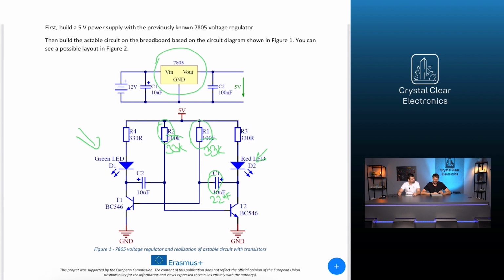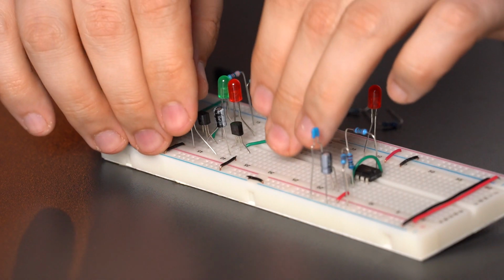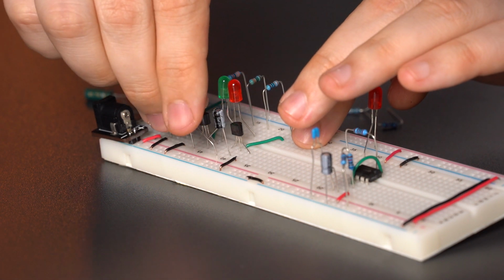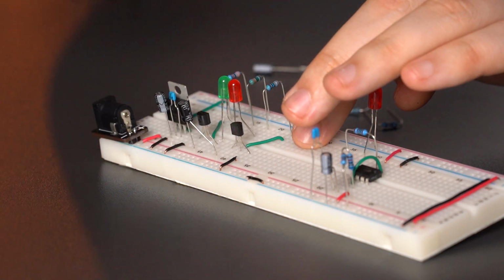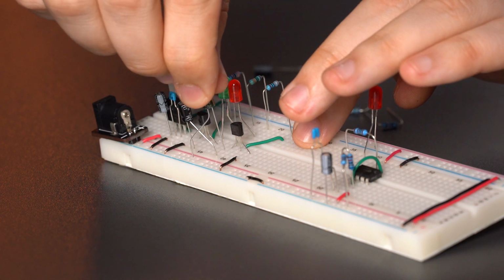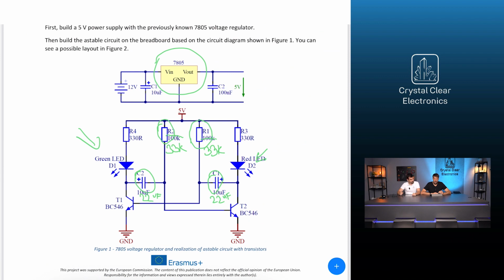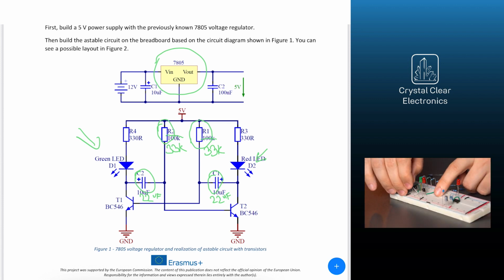You can experience the same with the D1 LED when you replace C2 with a 22 microfarad capacitor. If you replace both C1 and C2 with 22 microfarads, the blinking will be symmetrical and about half as fast as before. So the blinking frequency also depends on the capacity values.